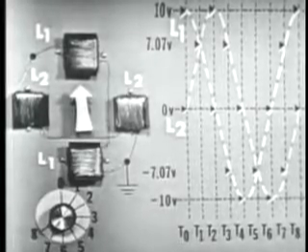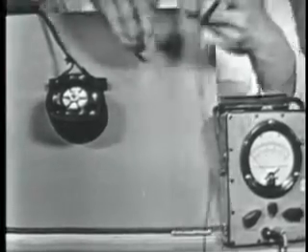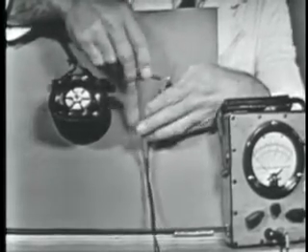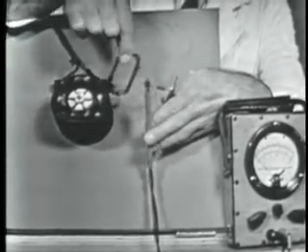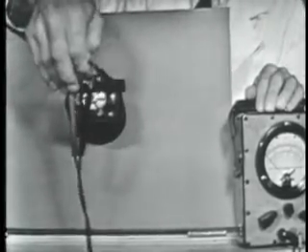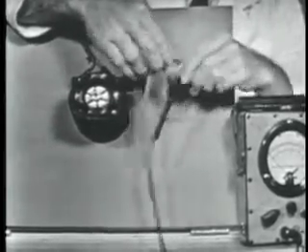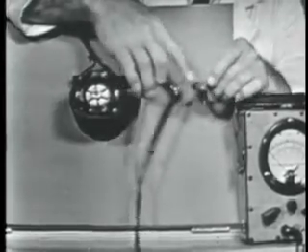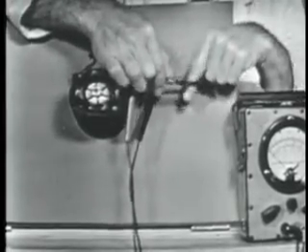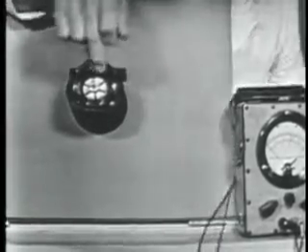Right. Now, I'll take item 4. All right. Help us out. All right, item 4, the rotor acts like a magnet. Well, it actually becomes an electromagnet and follows a rotating magnetic field because of induction. Okay, and we proved that with this little loop of wire, the resistor and the PSM6. We put the loop in the field windings, and the PSM6 showed us that we did have a voltage induced into the loop, causing current to flow. Once we had current flow, we know that the loop had to become magnetized and exhibit a north and a south pole. And once we get it magnetized, it has got to follow the rotating magnetic field.